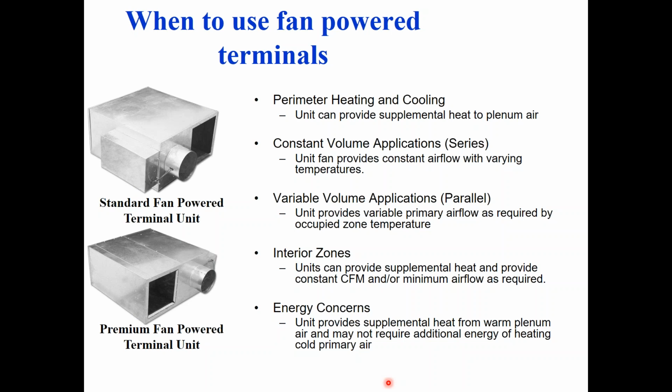Now they cost more than single duct boxes with heat because I gotta buy a fan in there, and they're bigger. They take up more space, and if you do things unintelligently, they could be a sound problem. They will also have some energy concerns from a fan standpoint, but if you do your duct design correctly, which we'll talk about here, your air handler fan can be reduced in size, specifically if you're using series boxes. Your air handler fan will be smaller, and you'll use these little individual fans, and combined, it'll probably be less energy from a fan standpoint.